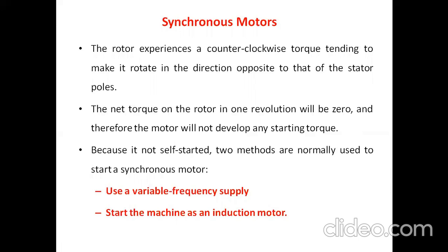To make the motor self-starting, we use two methods. One is to use a variable frequency supply, by varying the frequency of the stator three-phase supply. The second is to start the synchronous machine like an induction motor, by adding one more extra winding.